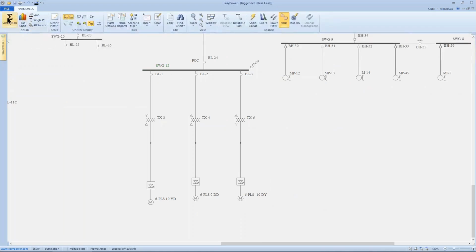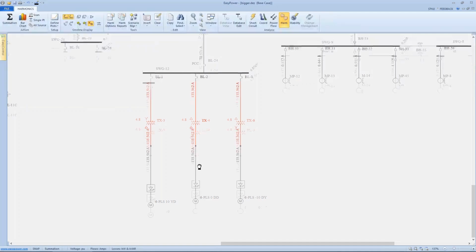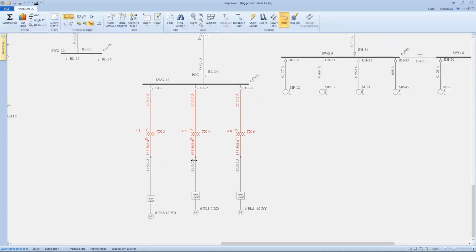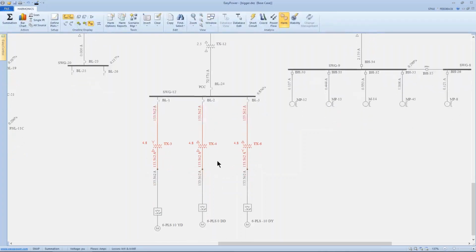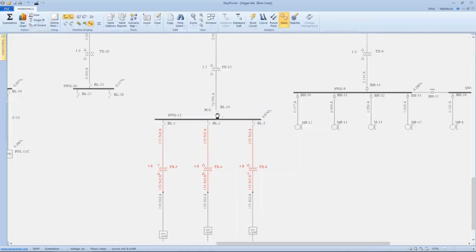The idea being now, if we come back to my harmonic simulation and we look at the summation of everything, we're seeing 135 amps of harmonic current in each of these legs, but when they total out, there's less than 75 amps total. So we're actually canceling the different phases, and part of the solution requires a K rating that accommodates these harmonics for our drivers.